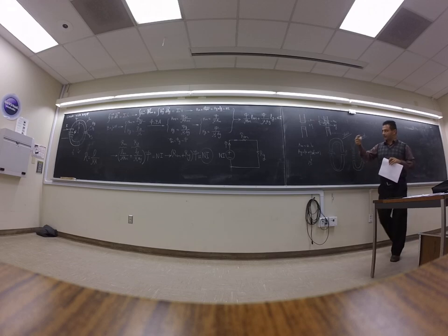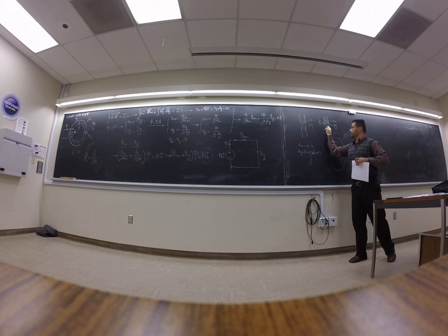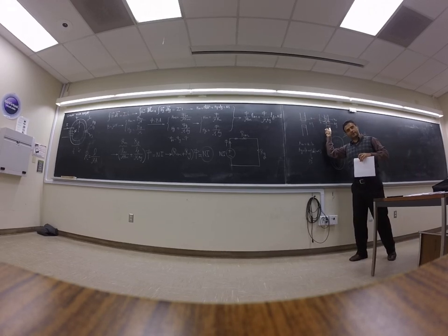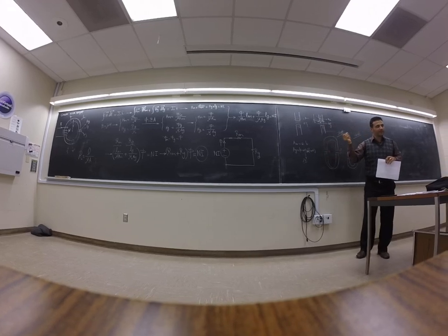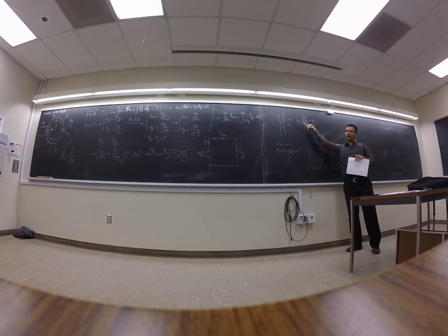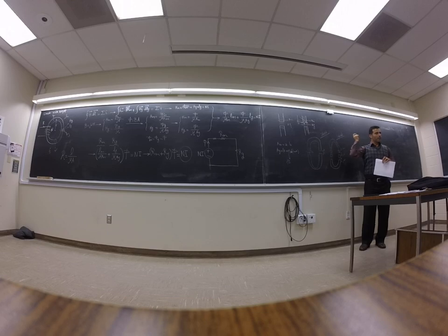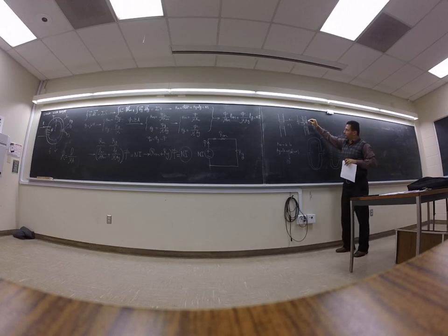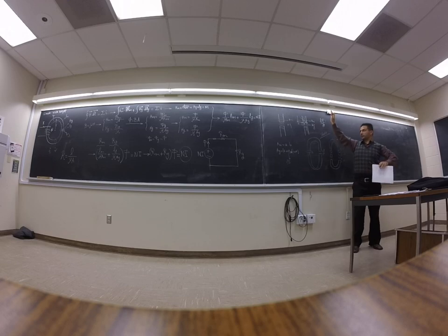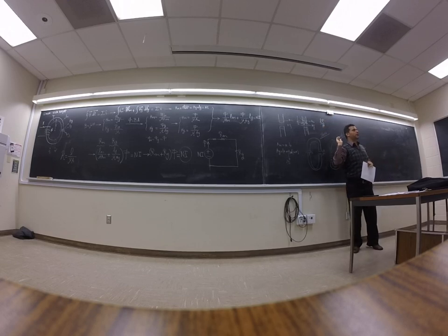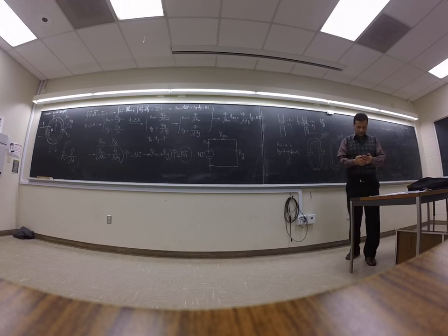Now they asked if this depends on the air gap. Yes, it depends on the air gap. And the reason this is important, maybe you ask why this affects the loss? Look at here, if the lines are completely straight, you don't have a dB over dt. The lines are good, but as soon as you start to bend like this, there's a dB over dt. dB over dt is going to translate to loss.